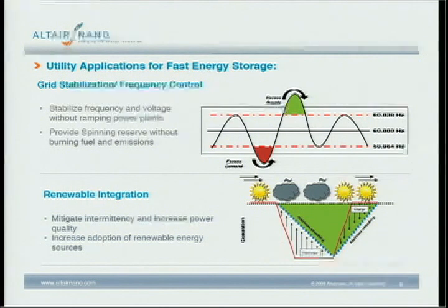What we're seeing down here is being looked at in very high penetration areas, where they're saying the wind is too erratic, the power output is too erratic. We're going to curtail that power because it is too erratic, or you work on smoothing the output of that system. If you could picture the wind farm and the battery system coming together, on the backside the power coming out of that is far smoother going into the utility system.